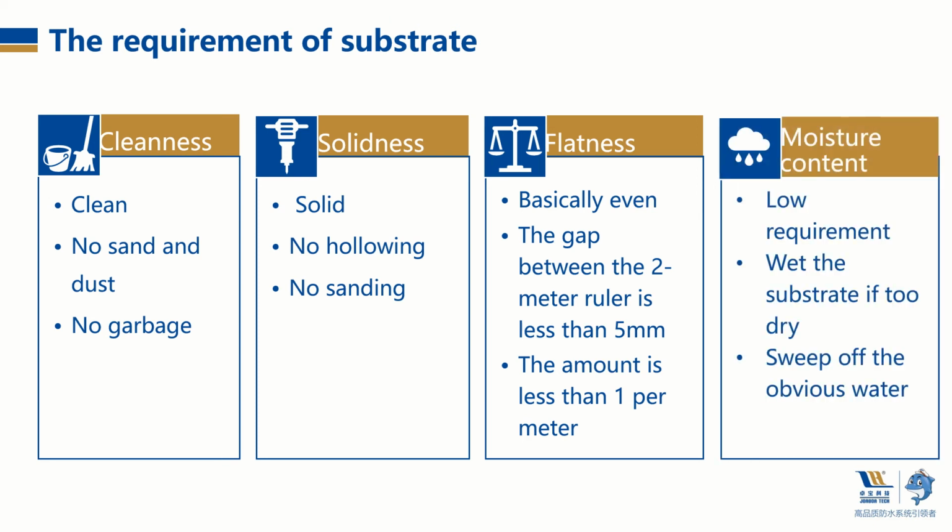Wet application is highly adaptable to the moisture content of the substrate. It can be applied on the wet substrate, and if it is too dry, wet it in advance. After rain, sweep off the obvious water.